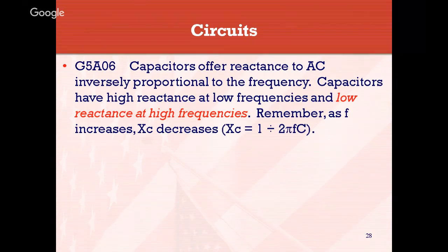Capacitors offer reactance to AC inversely proportional to the frequency, and that's why it decreases as the frequency increases. So capacitors have high reactance at low frequencies and low reactance at high frequencies. And if you remember, as F increases, capacitive reactance decreases, and there is your formula once again.